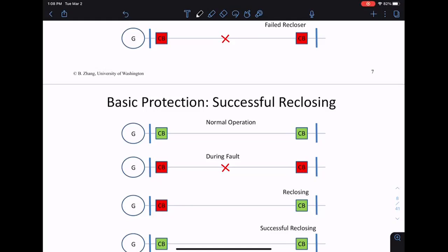When you put the breaker in, you have to set the breaker manually. You're the second in the sequence. So if you measure a fault, you wait for 0.1 milliseconds, then you try to reclose. All of this right now is actually set by hand. When you go in and install these, there's a little programmer, you program this, and there's not much real-time measurement communication going on in this sort of protection. So that's something to be aware of.